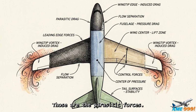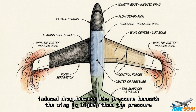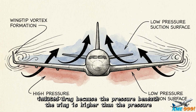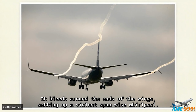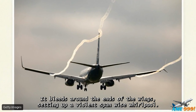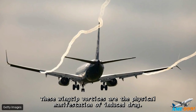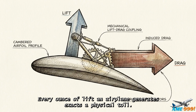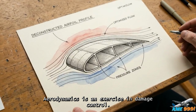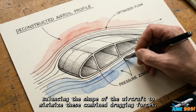Those are the parasitic forces, but there is another penalty intrinsically tied to the creation of lift itself, induced drag. Because the pressure beneath the wing is higher than the pressure above it, the air naturally tries to escape upward. It bleeds around the ends of the wings, setting up a violent span-wise whirlpool. These wingtip vortices are the physical manifestation of induced drag. They constantly pull energy away from the aircraft. Every ounce of lift an airplane generates exacts a physical toll. Aerodynamics is an exercise in damage control, balancing the shape of the aircraft to minimize these combined dragging forces.